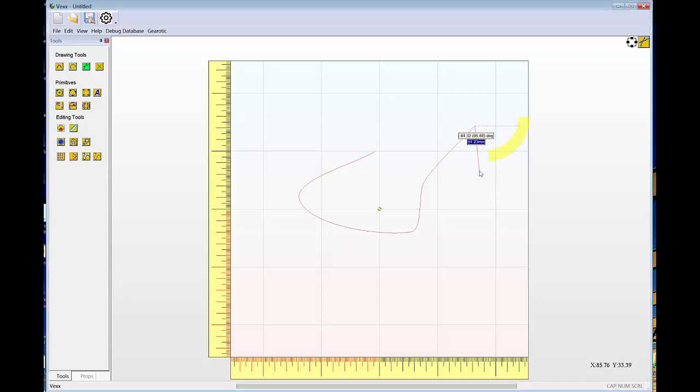At this point, we should talk about the right-click menu. When you right-click, you'll get a radial menu, and there's selections here where you could change between entity types. Here we have Bezier, arcs, lines, and at the top we have a check mark. A check mark means to complete the current tool, which means we can terminate a Bezier, but we're still in Bezier mode. If you look over here at the side, you'll see the Bezier is still lit up, so we can still type in more Beziers. Check mark will stop it.